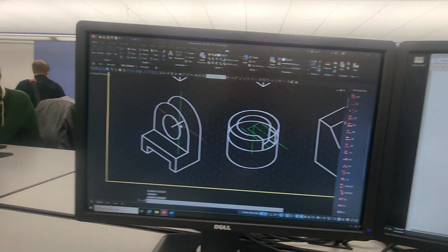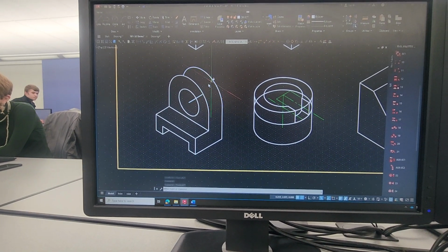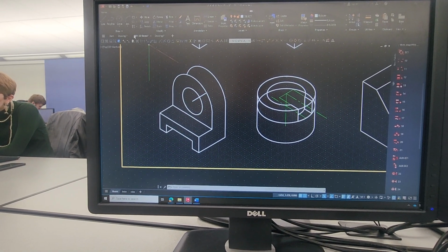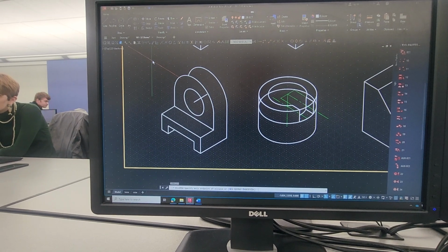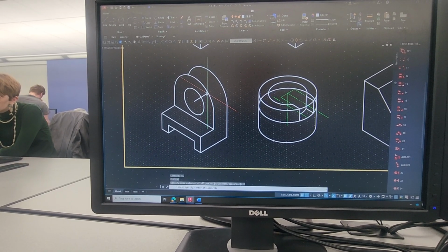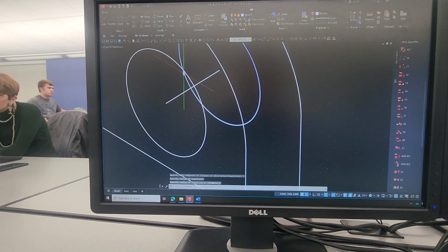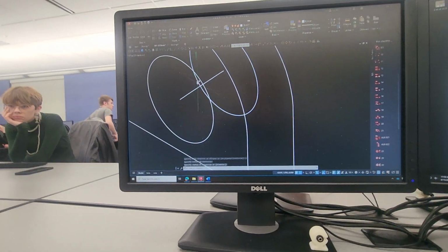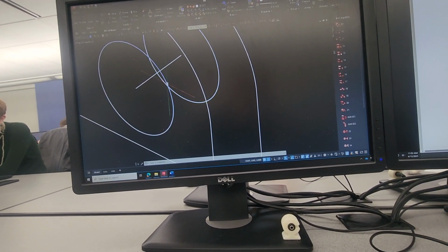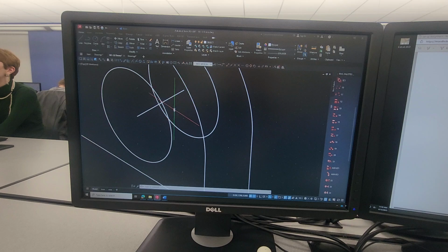Sometimes you need to set up some type of a skeleton to make sure you're getting the right points in order to make these things match. But you'll notice if I do another ellipse, ISO circle, come back down here, and click that endpoint right there, then I can make the exact same circle there. What am I seeing happen right there? I'm seeing through it, the back side of the thickness of that object.